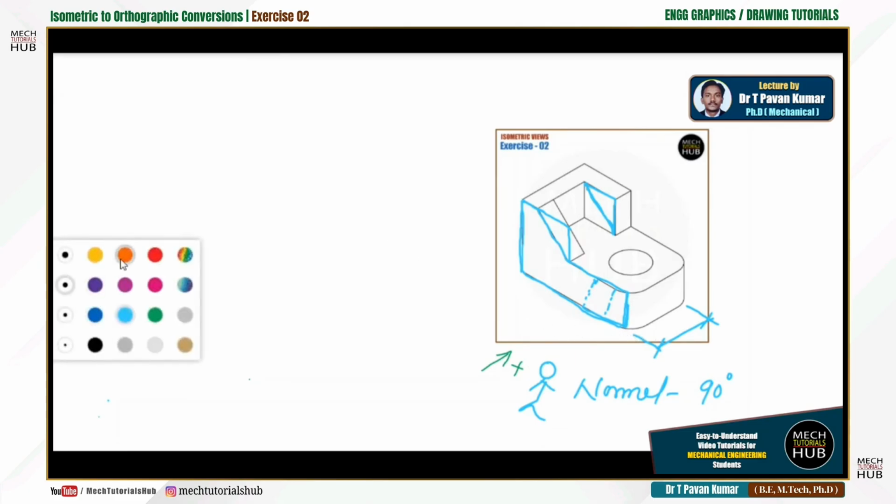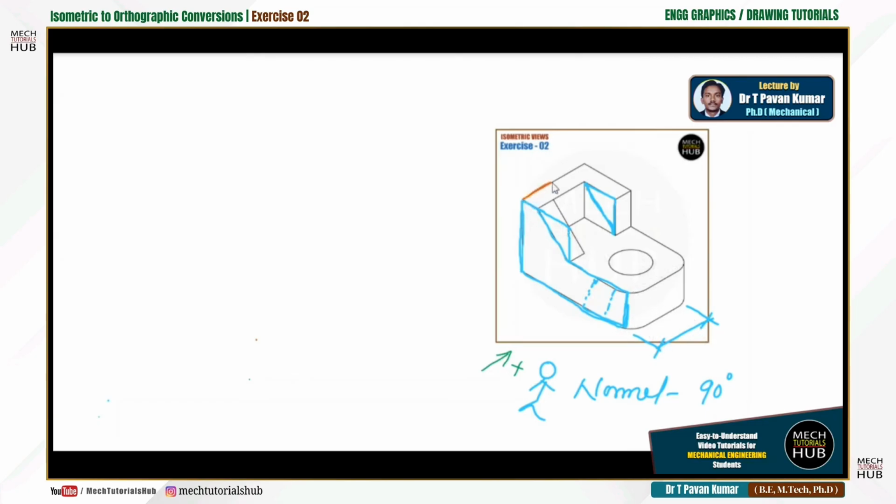If I go to the top view, if I change my position to the top, what is visible is this line, and again this smaller edge followed by a straight line, and this edge is visible. This top edge is also visible. But this height is not visible from the top. I can't feel this height because this is falling perpendicular. So this line is again colliding with this line, so this line is also not visible. There is a connectivity. Now I can feel that.